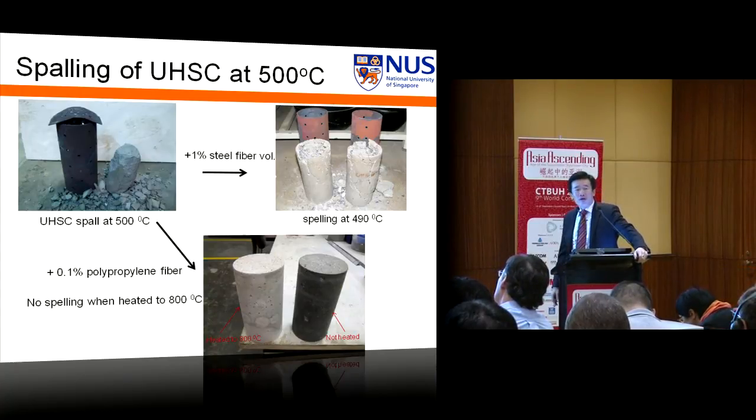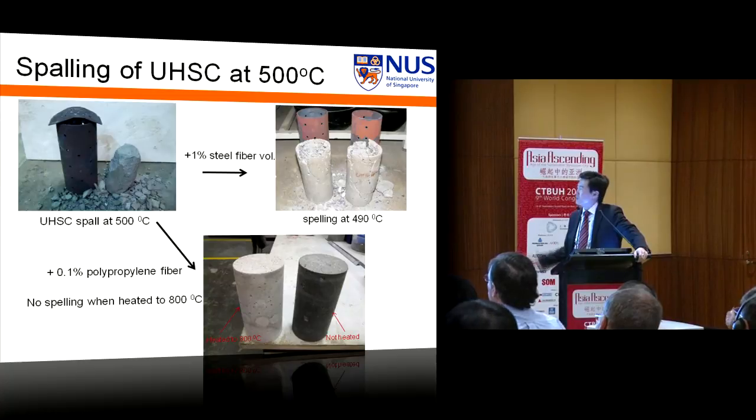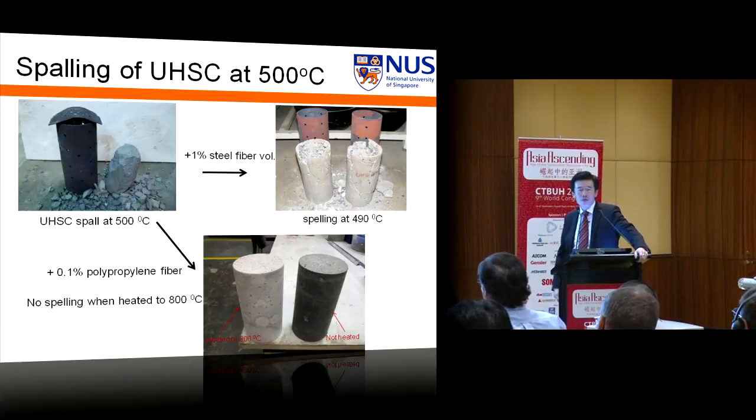Well, we say, okay, all right, then we put 1% steel fiber inside that. Try to reinforce the concrete a little bit using fiber. We heat it up. Close to 500, again, it explodes. So that means the steel fiber doesn't help in providing fire resistance to our concrete.